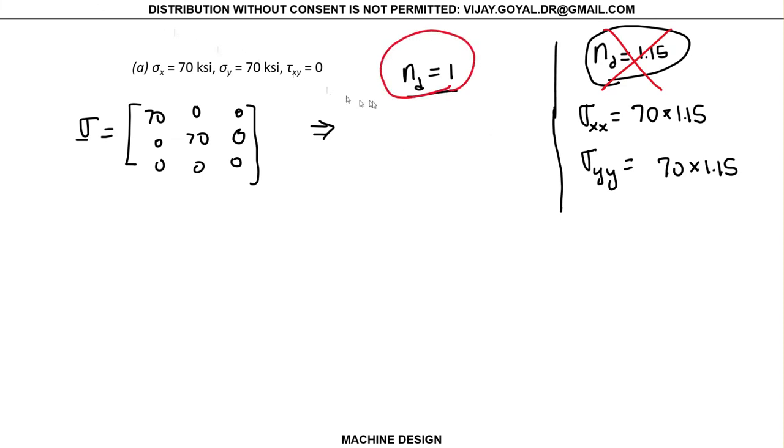Second thing you want to do in the problem is find your principal stresses, and tau max. That just comes from your state of stress and your principal stresses. Once you have that information, we have 3 theories to work with. The first theory is the distortion energy theory that requires me to find a sigma equivalent.